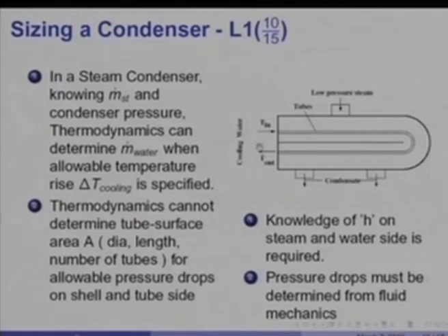The difference T out minus T in is specified simply because often the temperature of water coming out of the condenser is let off into a pond or a creek, and in order to save the marine life, for example, one would specify that T out should not exceed 32 to 33 degrees centigrade, because if it is hotter than that, then it is harmful to marine life.